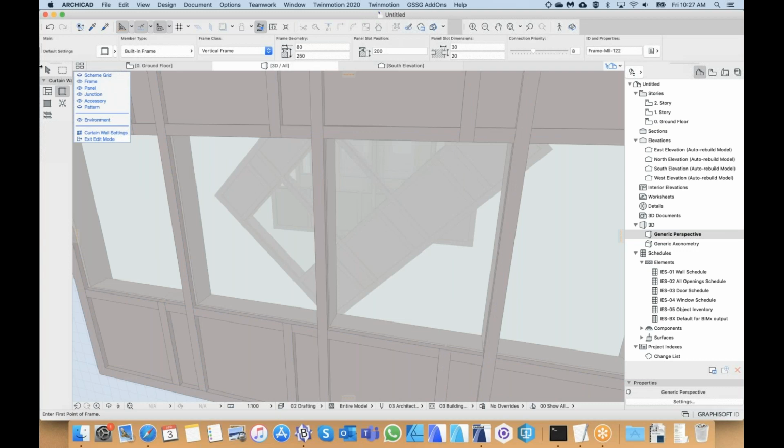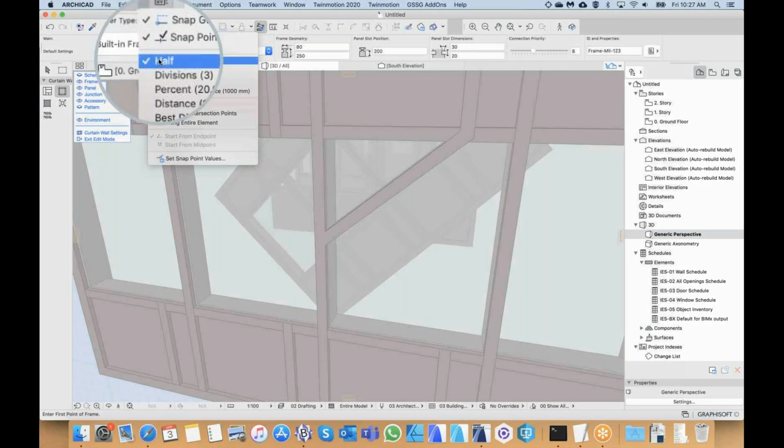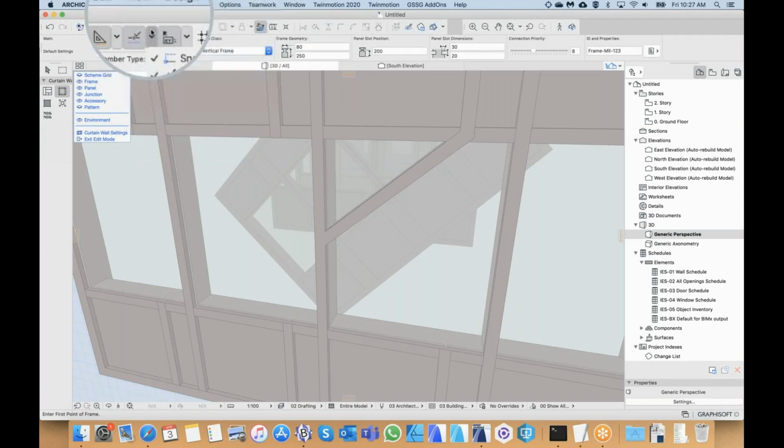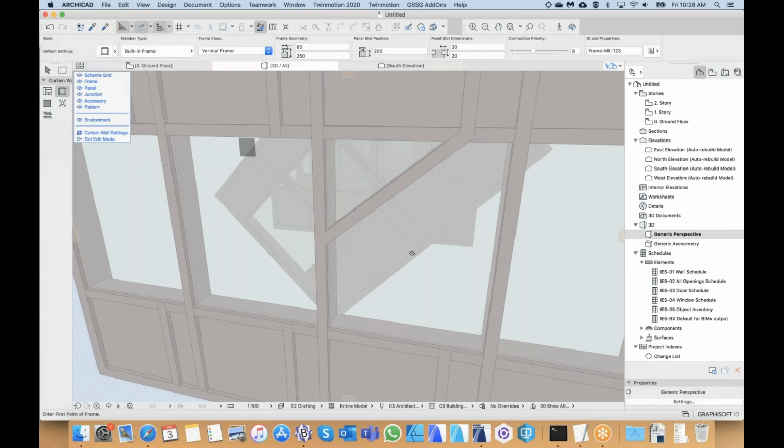Sorry, I was testing something quickly. Okay, so I'm going to choose the frame, and now I'm going to go from this node, hover over my vertical frame till I find the center point. When the cursor turns to a solid pencil, click. Again, to get the center point, just make sure that we select half from this pop-up and choose half. So like what we did earlier in the week. And then I'm going from a tick mark to a solid pencil here.